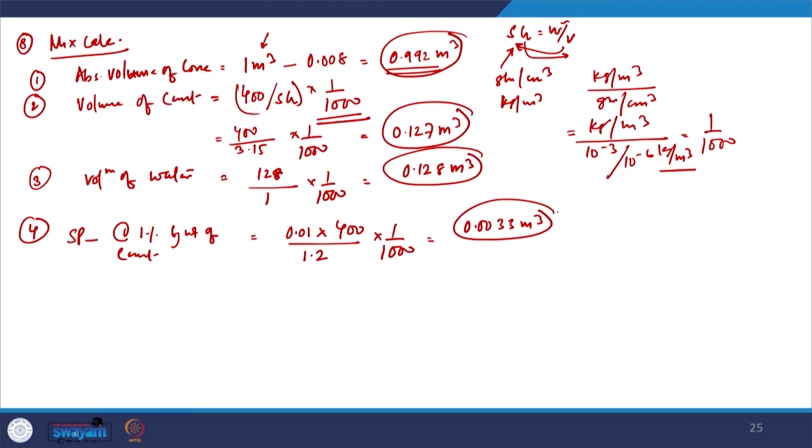So, now we have the volume of all the materials, and then we also have the volume of coarse aggregate and fine aggregate, but that is not by the volume of concrete, but by the volume of the total aggregate. So, now I have to divide the remaining volume to those aggregates.